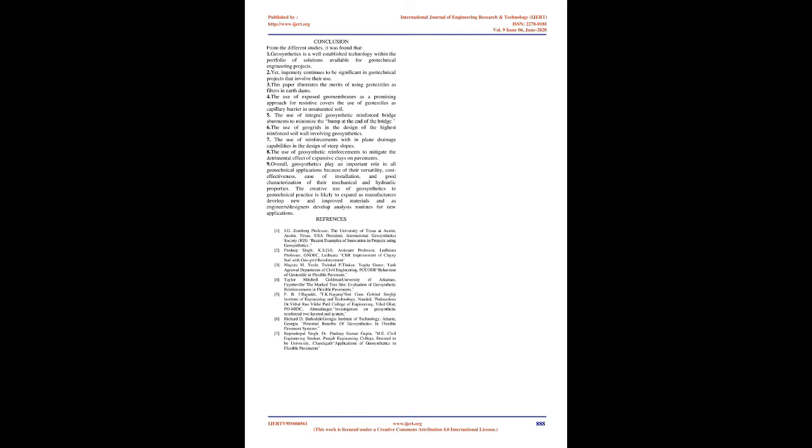Richard D. Barksdale, 1989. This study was primarily concerned with the geosynthetic reinforcement of an aggregate base of a surfaced, flexible pavement. Separation, filtration, and durability were also considered. Specific methods of reinforcement evaluated included: 1. Reinforcement placed within the base, 2. Pretensioning a geosynthetic placed within the base, and 3. Pre-rutting the aggregate base with and without reinforcement.